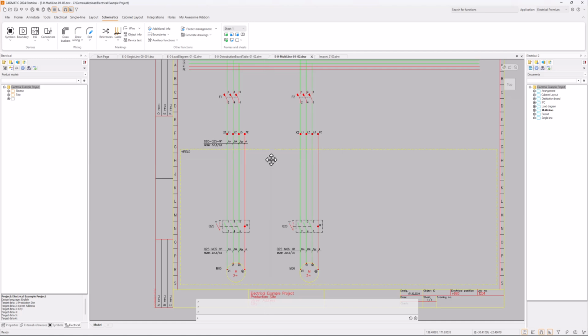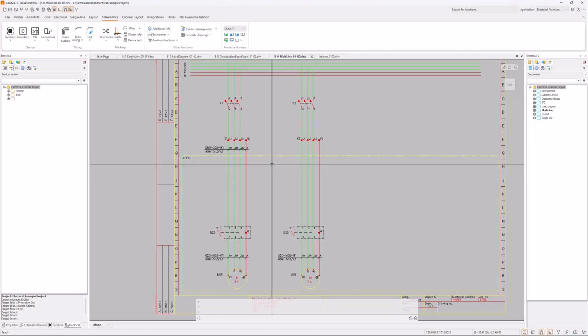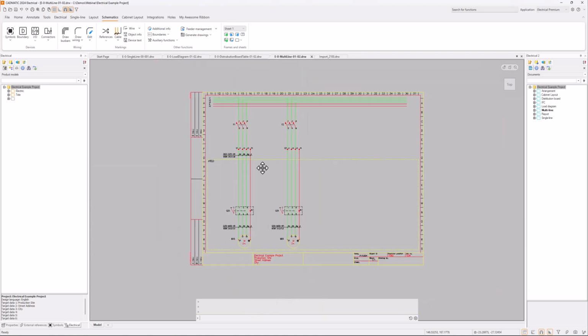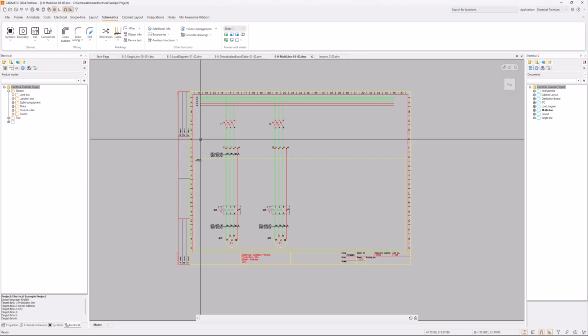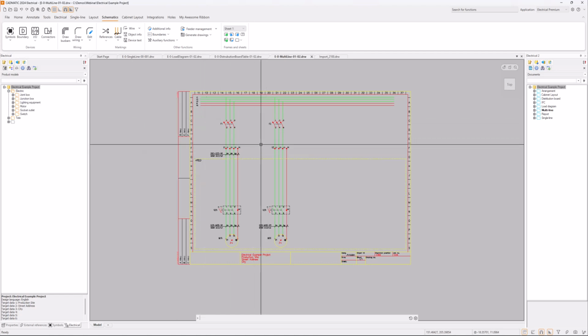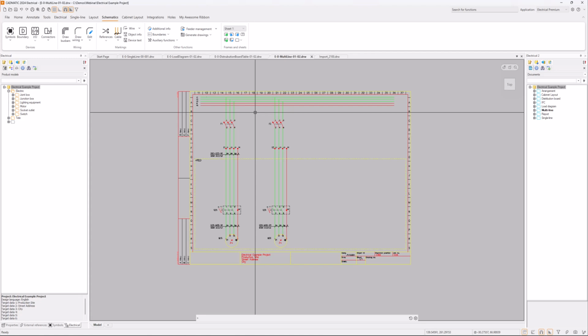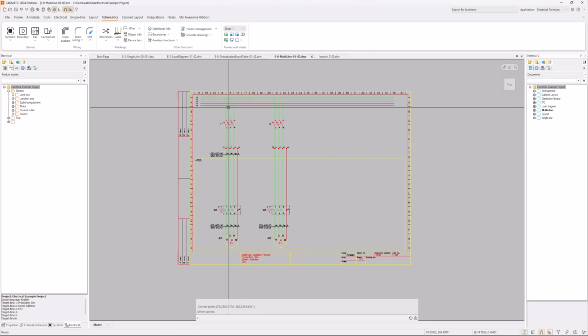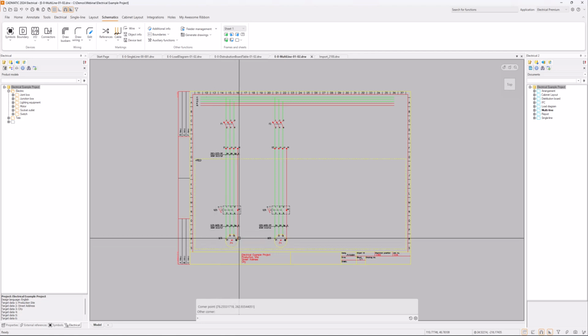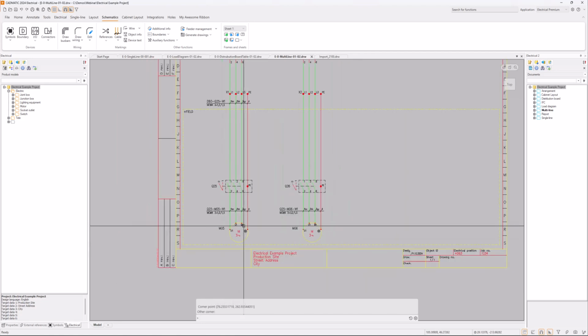So as I explained, the single lines are for the cables, multi-line is for the wires. So it is here. So what we have is the bus bar. Now it has all the 5 wires. It has a protective, earth, neutral, and 3 phases. And all the 3 phases are also going downwards until the motor.